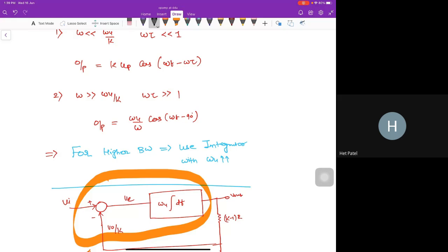That's the UGB that we will calculate when we analyze the circuit at the MOS level. But from this block diagram, I just want to tell you that my omega u is making the boundary between the strong feedback and the less feedback, and based on this, my settling time and even my ringing stability depend. That's the point. Please note it here.